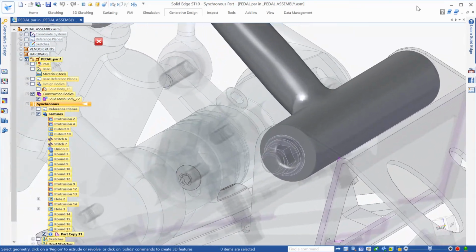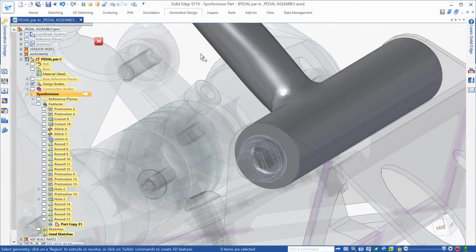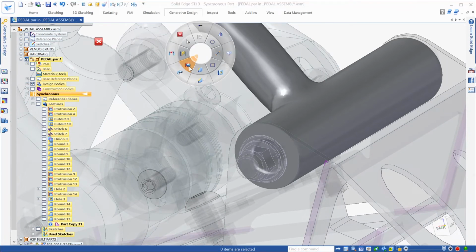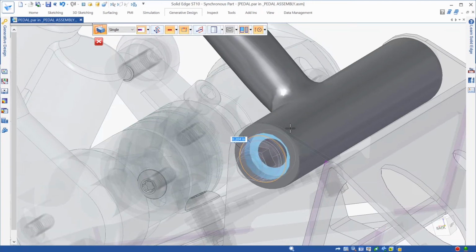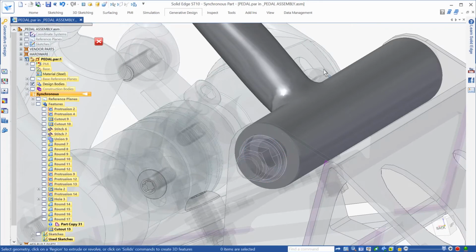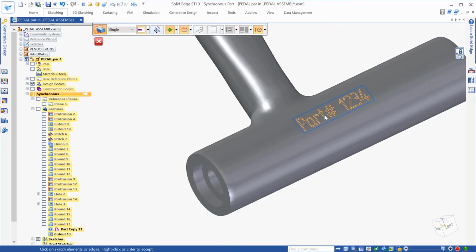The huge advantage in using Solid Edge to create and work with these generative designs, which are essentially mesh models, is when it comes to the creation of additional features that the design may need. With Solid Edge, adding and removing material is simple and fast. For example, a cutout can be added to the lower boss for the purpose of placing a bushing. The use of standard modelling tools makes this process quick and easy by picking up on background parts in the assembly. We'll also add some geometry too.